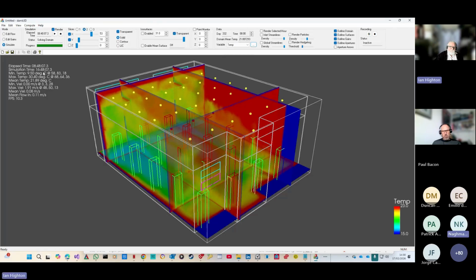Let's just summarize. So you're simulating dynamically a classroom here from 8 in the morning till 6, a whole day, in a matter of already 5 minutes. Yeah. And that's proper full-on CFD simulation for a whole day, dynamic hourly, in just a few minutes. That's basically the summary of this, and the inputs, or rather the boundary conditions, are coming from your dynamic simulation model, right?